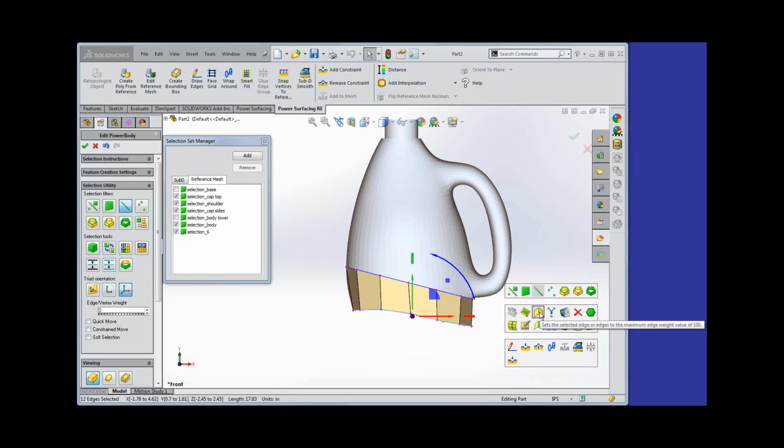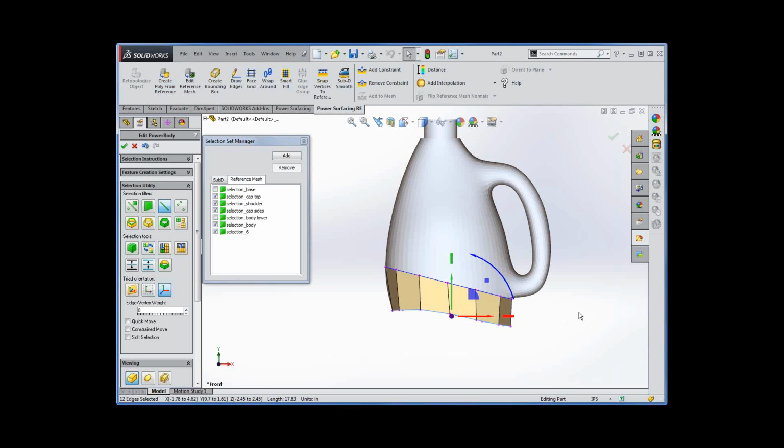Now, if you're just making monsters and ogres and things with sub-Ds, you probably have very little use for a hard edge. But when you're doing more industrial sort of design and things, a hard edge is something that's a big part of some of the design. So having done that, now I'm going to turn on the lower body, and holding my A key, I'm going to do a little bit of an extend.